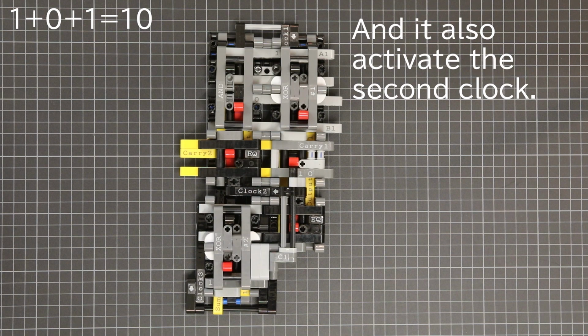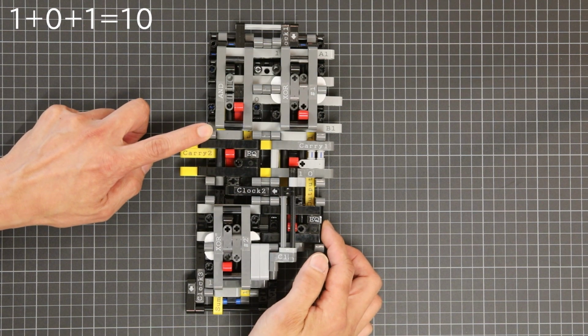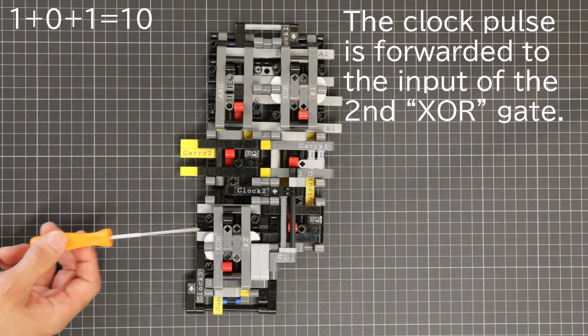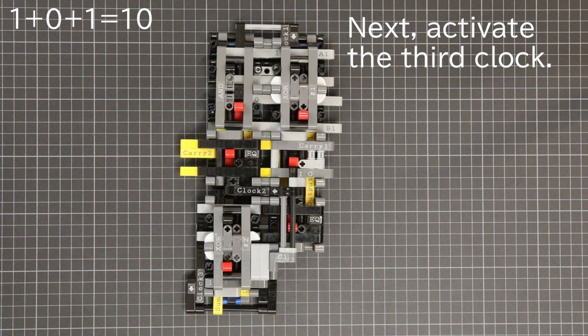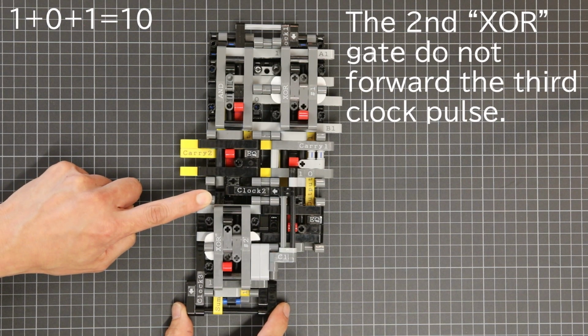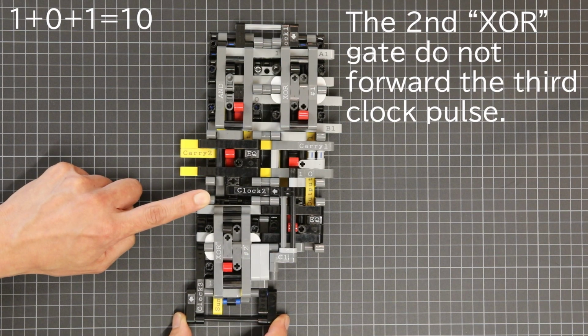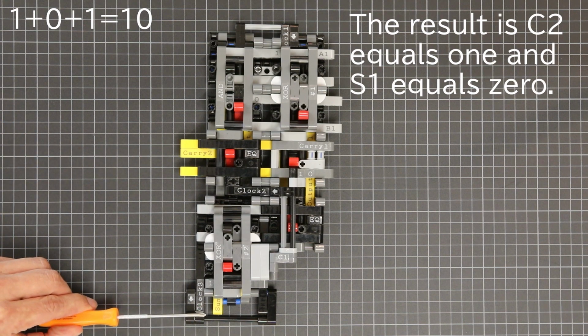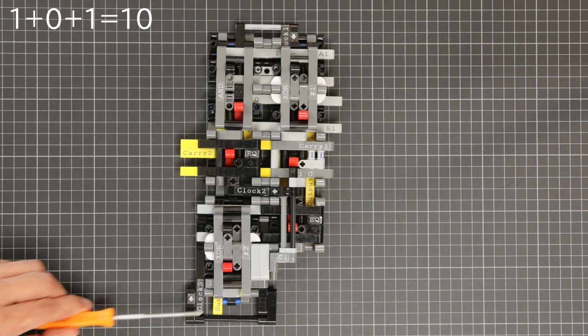And it also activates the second clock. The clock pulse is forwarded to the input of the second XOR gate. Next, activate the third clock. The second XOR gate does not forward the third clock pulse. The result is C2 equals 1 and S1 equals 0.